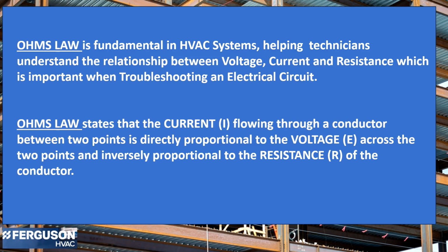Ohm's law is fundamental in HVAC systems, helping technicians understand the relationship between voltage, current, and resistance, which is important when troubleshooting an electrical circuit. Ohm's law states that the current, or I, flowing through a conductor between 2 points is directly proportional to the voltage, E, across the 2 points, and inversely proportional to the resistance, or R, of the conductor.